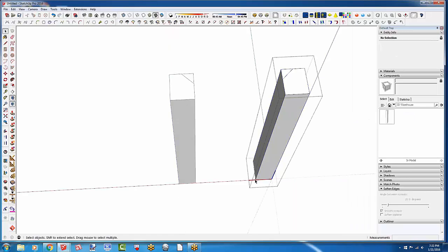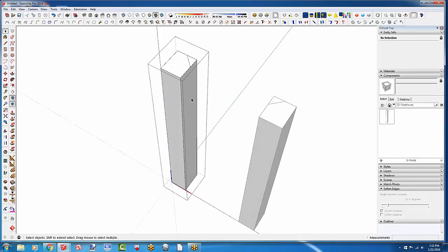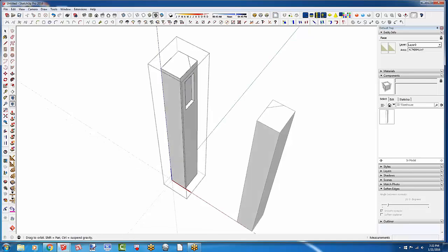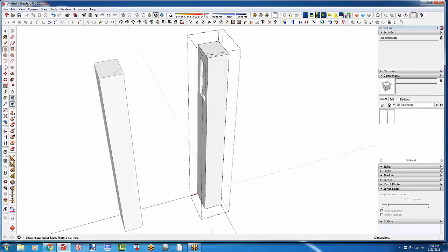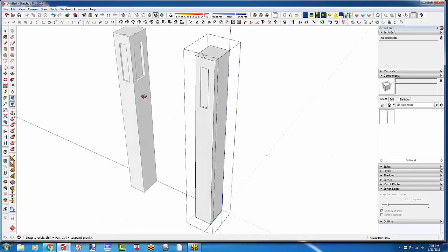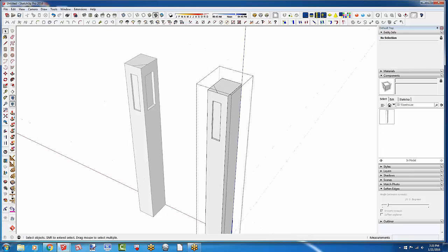By the way, the component has its own axes that are aligned with the model axes when you make it. So again, if I put the mortise in there, I'm not making it very deep obviously, and I put one here, you see I've got the mortises in the proper places on the mating leg.